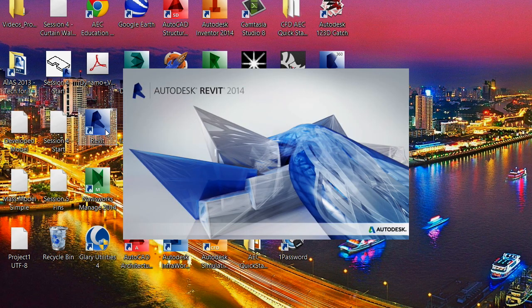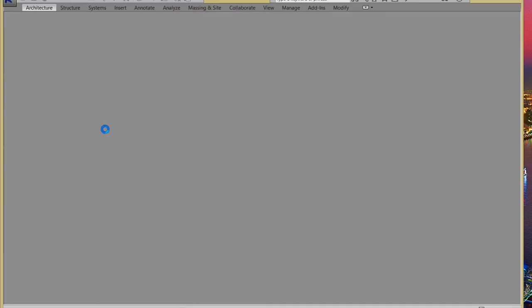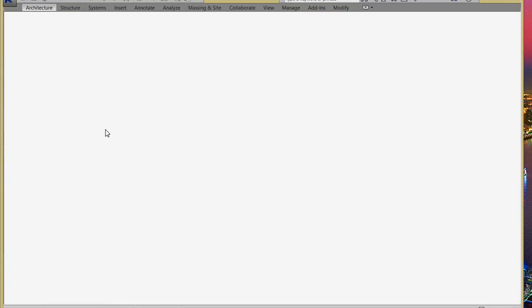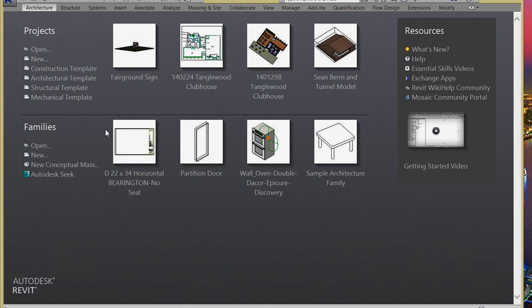Here's the basic idea. We've been going through and placing the basic elements of an HVAC system. We've been putting in some registers, an air handler, and some ductwork, and tying these things into systems. The cool thing about tying them into systems is that as soon as they understand themselves as elements of a bigger system, where all the loads ratchet up and feed into some main distribution or handlers that ultimately feed the entire system, you can then start doing some sizing. So let me open this one.